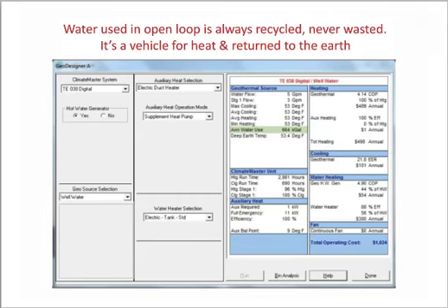Here's an example I highlighted. This is from our particular sizing software, GeoDesigner. This particular unit was a 3-ton. You can see at the very top the water flow at 5 gallons per minute. And one of the things that you want to be prepared for as an installer, as a contractor, as an engineer, you want to pay attention to the annual water use. And yes, that one in that example is 664,000 gallons. Yes, that is a lot of water.